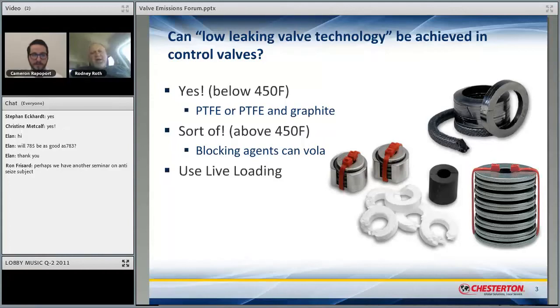Okay, so there's not a packing test on the ISO side. So if I test my packing in one manufacturer's valve, and someone else tests theirs in another valve, and then someone tests in a third valve, we could all have results, and they could be close or different. But the reality is, they're all different because it was 3 different valves with 3 different manufacturers with 3 different designs. So you really can't compare that data effectively.